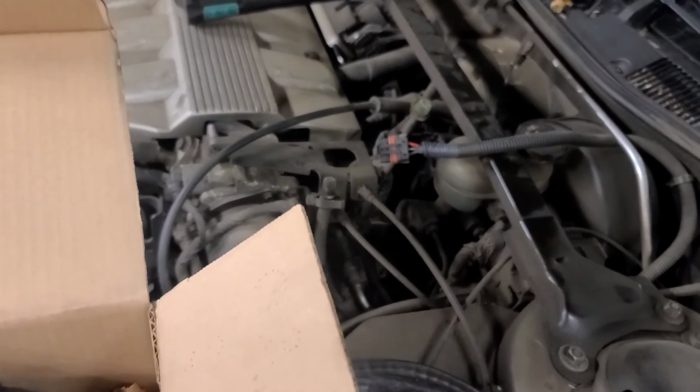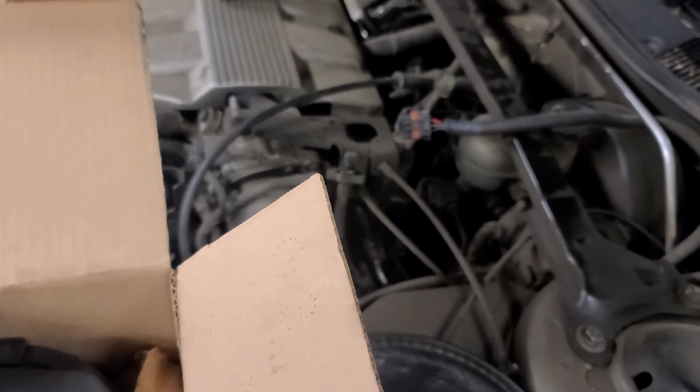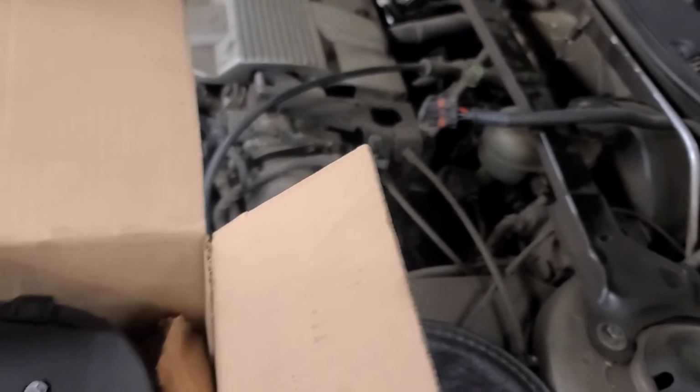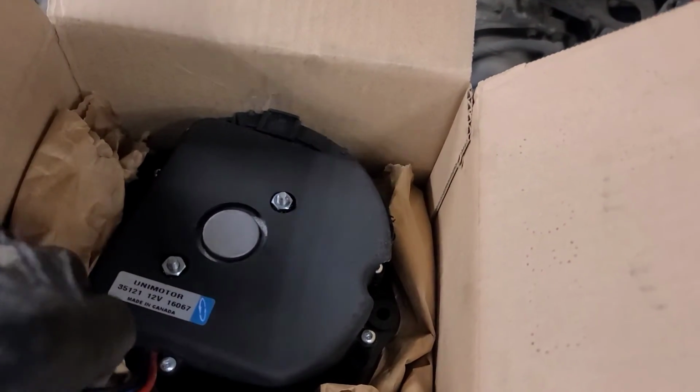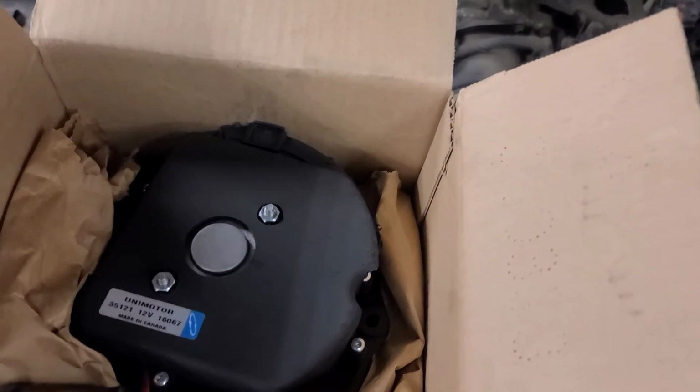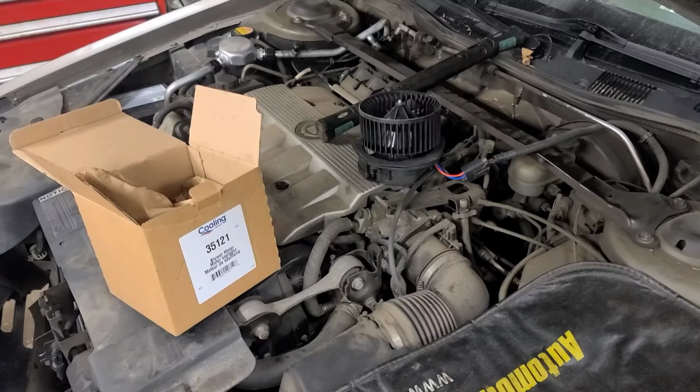I'm going to plug it into the connector here and set it on top of the engine bay here and see if it runs. Now, normally you wouldn't run the heater blower without it being in the blower housing because it cools the blower resistor, but the blower resistor per se is built into this thing. It's electronic, so it's transistorized, and we're only going to run it for a few seconds. Now, I also learned working on this thing last time that it actually has to be running for the blower fan to run. It didn't run with just the key in the on position, unlike most.